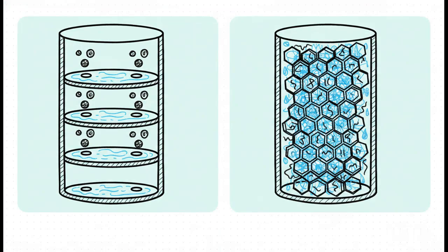There are essentially two main categories for the mechanical internals: plate columns and packed columns. Packed columns use beds of specialized structural packing material to create a ton of surface area for the liquid and vapor to interact. Plate columns, on the other hand, which are incredibly common, use a series of precisely spaced stacked trays. The lighter hydrocarbons vaporize and actually flow up through holes in these tray plates, making direct contact with the liquid resting right there on the tray.